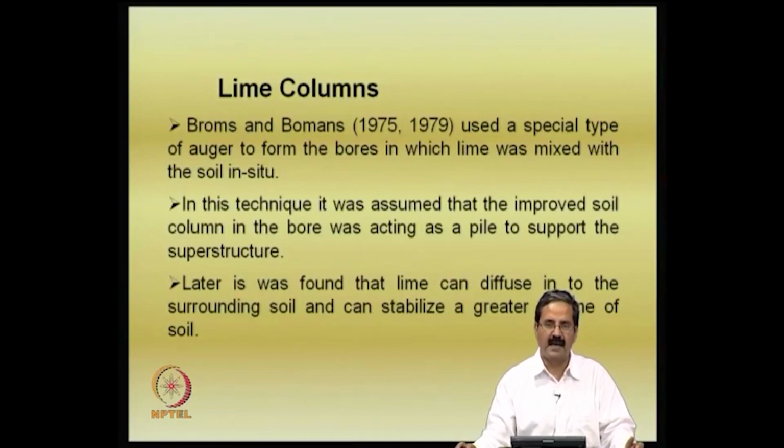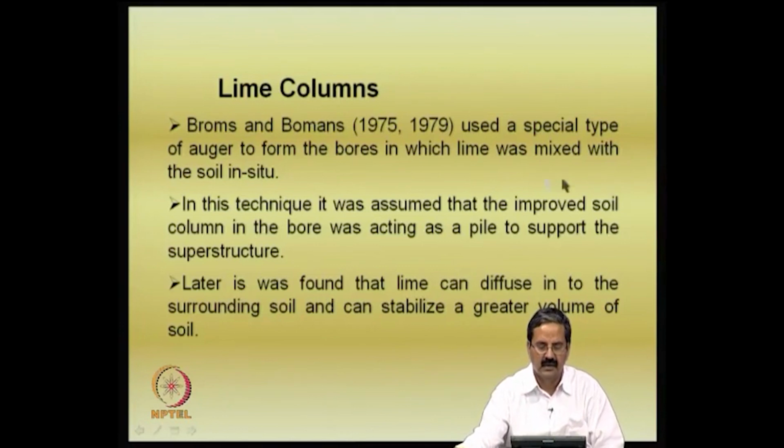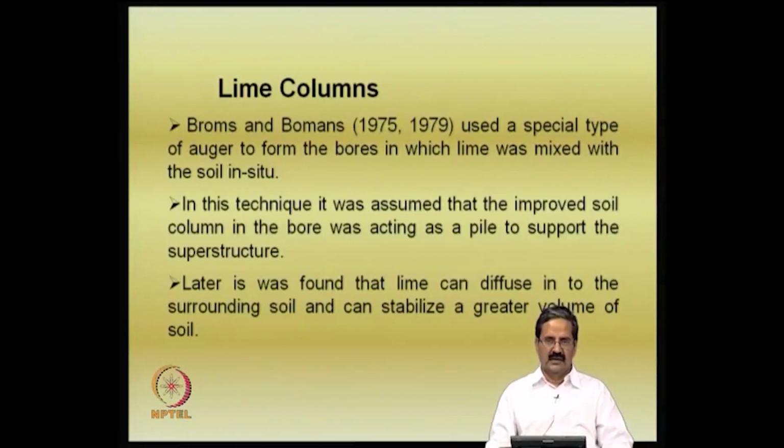But if you are talking about embankments, say 5 meters high, or foundations loading soft soils, you have to treat the soft soil in some manner. So, of the alternatives we discussed, like stone columns and other methods, lime columns are also very important. The advantage is that in expansive soils lime columns are definitely better, and in soft soils lime columns could also be used. Of course, you have other techniques as we just discussed, prefabricated vertical drains and stone columns.